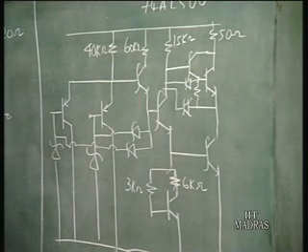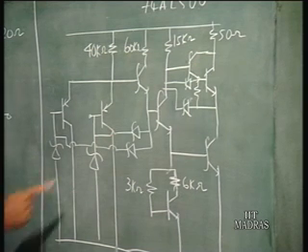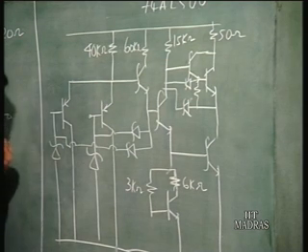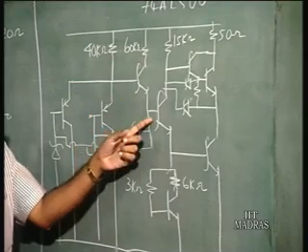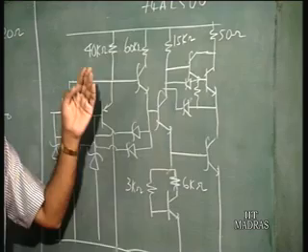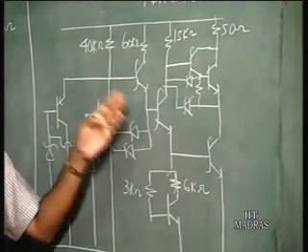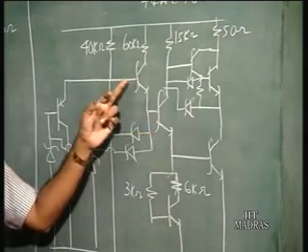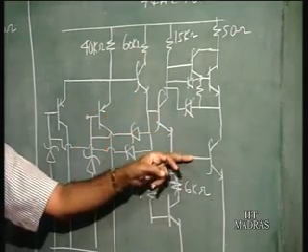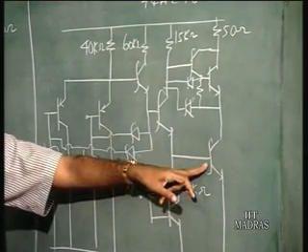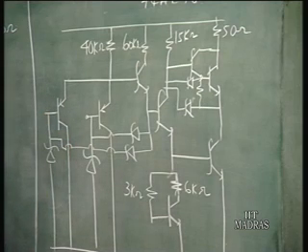Now the purpose of introducing this additional transistor is to have some additional current gain. Normally, when this transistor turns on, you have to turn on this transistor. So if you put one more transistor, this entire combination of transistors will have an additional current gain. So this transistor is going to switch on faster. An additional transistor has been introduced here for that purpose.